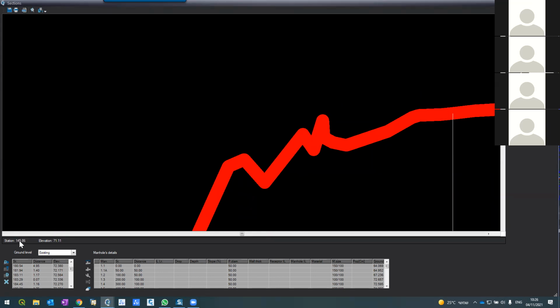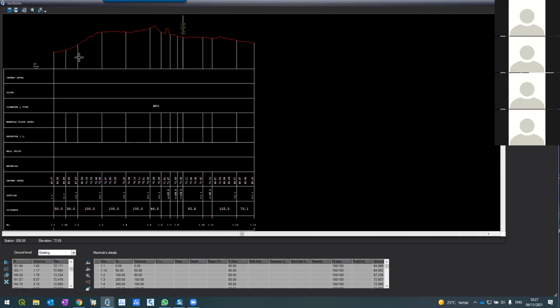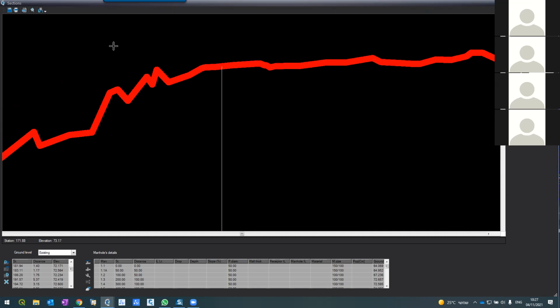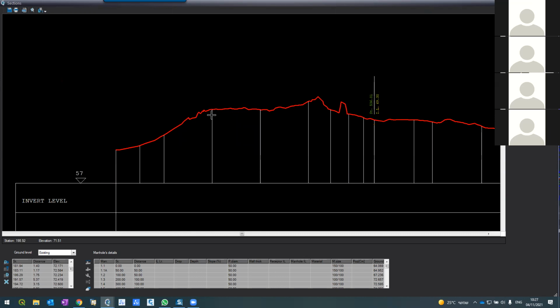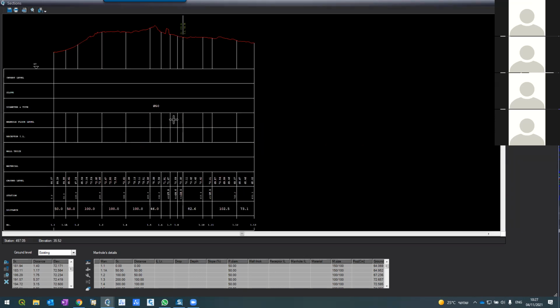I'm looking at 183.39. Where is it? Here it is, 39. Not exactly 39, 29. Standing on it, right click with the mouse, delete row. Even this one can be deleted. And I'm sure it flattens this place a little bit. This is the method. Okay, I have the existing ground level, but of course I want the road's level.